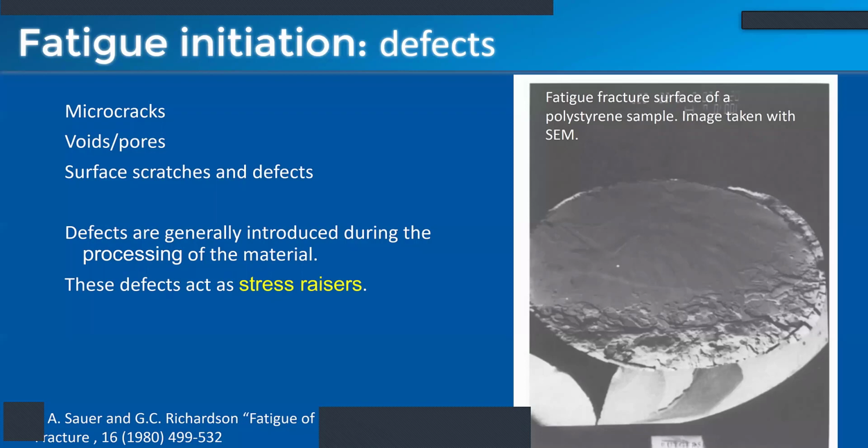So we're always operating under the yield stress, especially for a situation where you have to do repeated loading and unloading. But even at low applied stress, it can translate to something that is locally higher than the yield stress because of stress raisers. And when it's higher than the yield stress of the material, obviously the material starts to fail little by little. That crack propagates until we get catastrophic failure, catastrophic rupture of the device. Good.